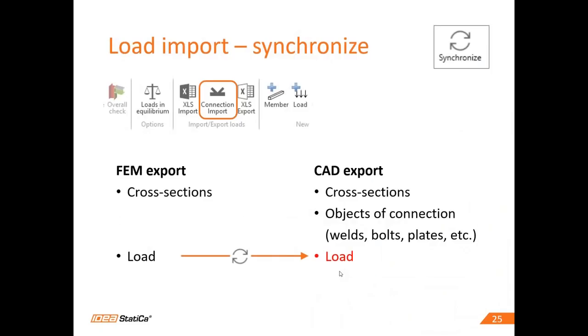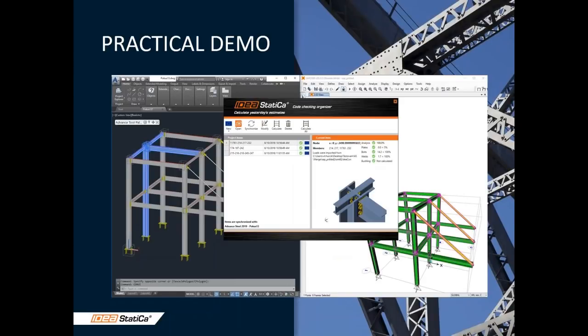What we have also prepared is quite a nice new feature: the synchronization of the load effects between the IDEA StatiCa projects. Once you create the connection from the FEM application, you can easily import the load effects into another project which was created from a CAD application. And how does it work?